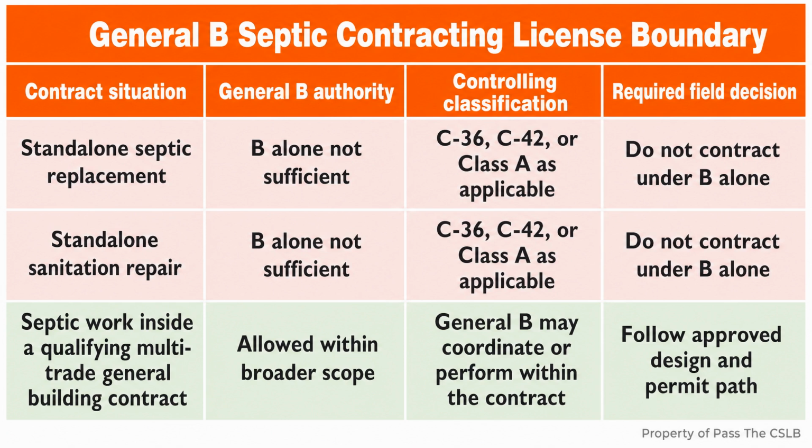A percolation test measures how quickly water moves through the soil. The result is expressed in minutes per inch of water drop. For a standard Tier 1 disposal area under the statewide policy, the supported range is not faster than 1 minute per inch and not slower than 120 minutes per inch. That range is easy to memorize if you think of the soil as having a speed limit.